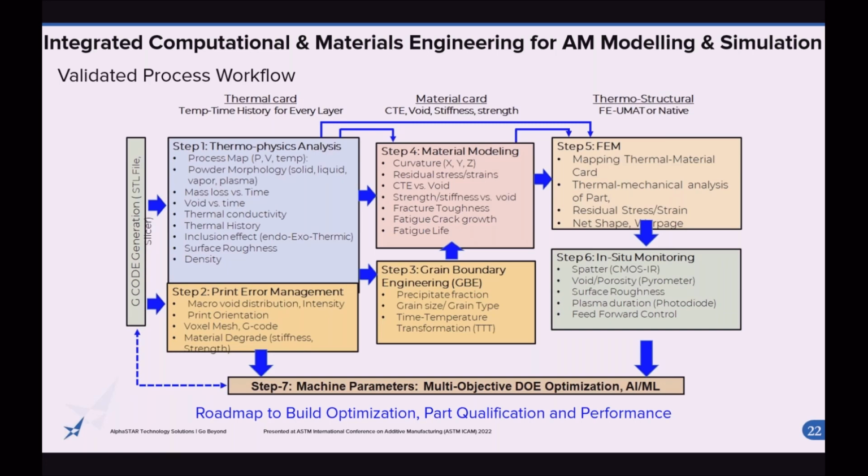And then with the help of finite element code, we can assess warpage, distortion, net shape, questions related to quality of the AM build, including residual stress and residual strain, and how that impacts not only build quality, but is a further step toward as-built part performance.